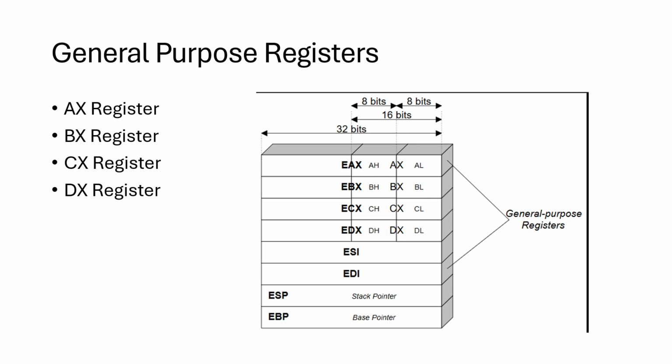The same way we can address as we had discussed for AX, and it is the only general purpose register that can be used as an index to extend addressing. Another common purpose for BX is for computations. BX can also be combined with the data index and source index as a base register for special addressing.